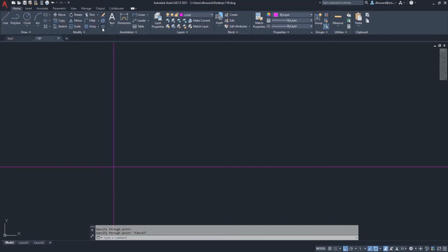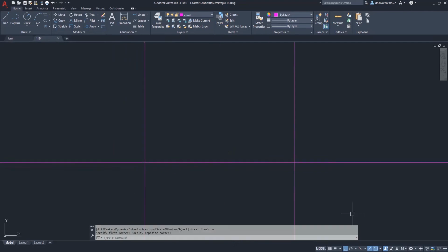So I'm going to go to my offset. I'm going to type in 3.875, enter, click the line, and click over. I'm going to zoom in just a little closer here. And now I have the centers of the two holes that are in that top view. They're even more important because they're also the centers of the arcs that make up the outside profile here. So I'm going to go to my object layer and show you what I'm talking about.